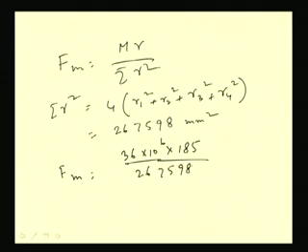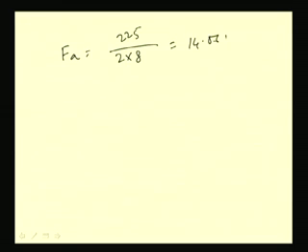So, after calculating all this, we will get the value as 24.9 kilonewton. So, force exerted on the outermost rivet due to moment is 24.9 kilonewton. This is one force. Another force is due to the direct load, that is, direct load applied 225 kilonewton, and total rivets are 2 into 8, means 16 rivets. So, this is coming 14.06 kilonewton.